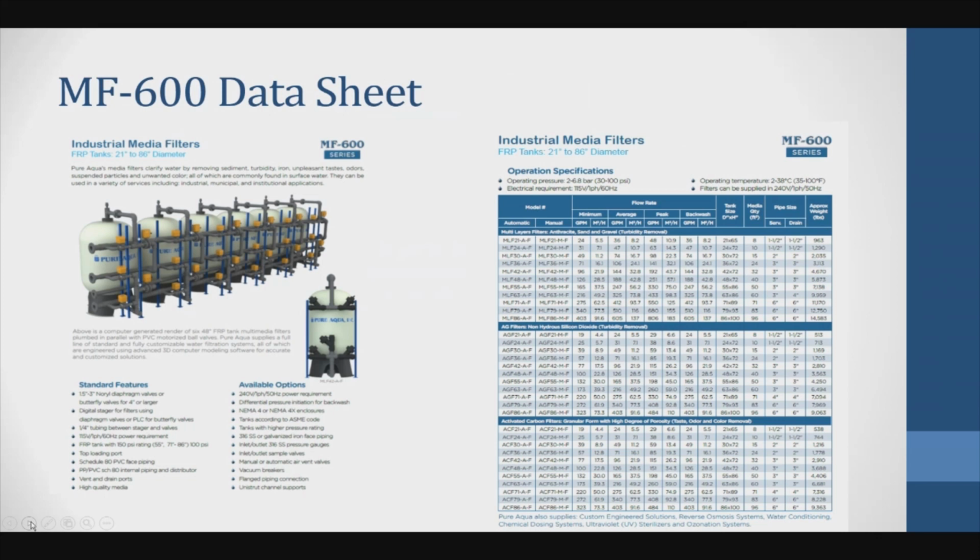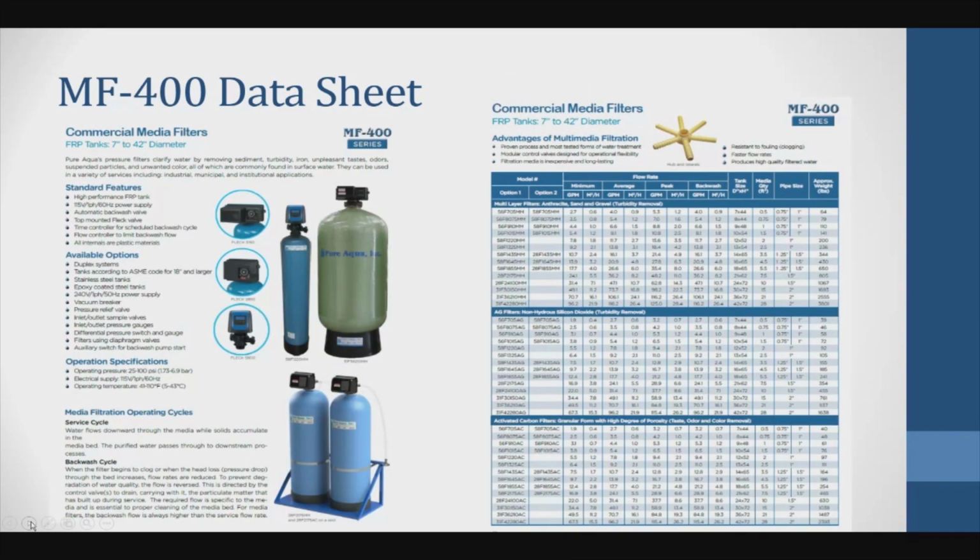Is it going to stop the reverse osmosis? Most probably it will, unless the customer asks for a standby filter, where it's not going to interrupt the operation of the entire plant. This is a smaller filter where the control valve is top mounted, and usually those are used for a small commercial reverse osmosis system.